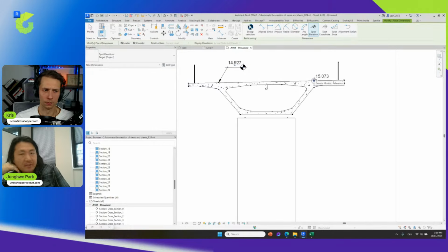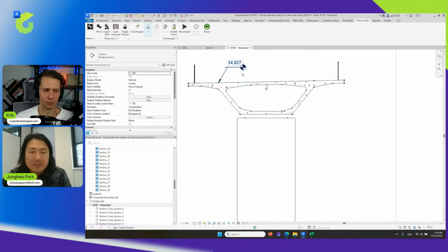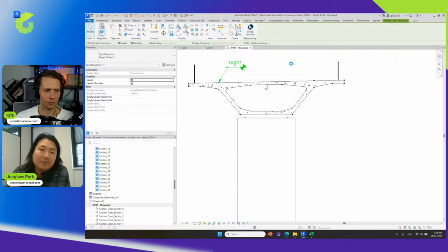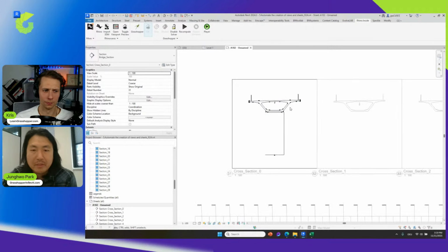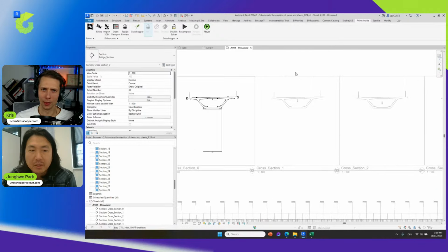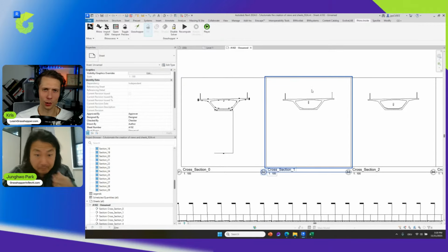and surfaces as dimension references, but actually you can even automate the dimension process using Rhino.Inside Revit, which is a little bit tedious because you always have to reference the constructed Revit geometry of Revit elements, such as vertices, edges, and surface faces. But if you have a structured pipeline, it will work, and those dimensions will also always be updated accordingly. And this is what we are showing in our